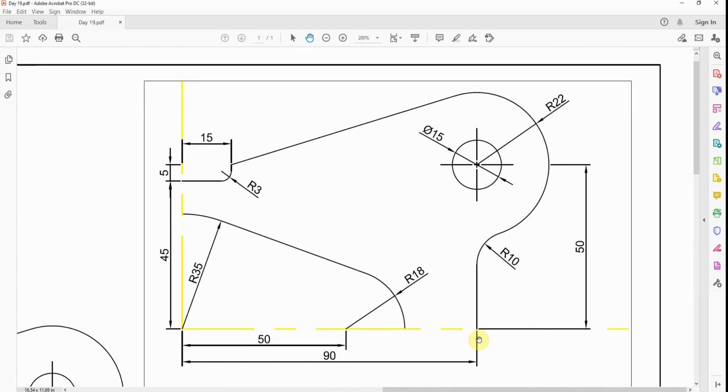Okay, and we have a secondary point from that same line, which we'll reference in our center point, which is 50. Other side, 45, 5, which will match up to 50, and then we've got some radiuses and components from center points. Again, we can use different tools. We have radiuses from center, radiuses where we don't know the center, so it's using a bit between the circle tool, arc tool and fillet tool.